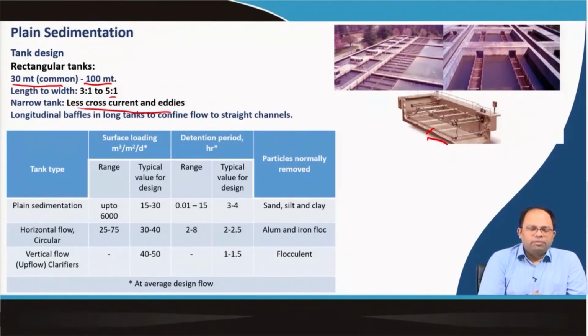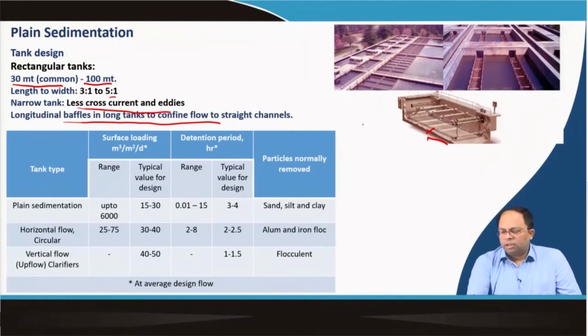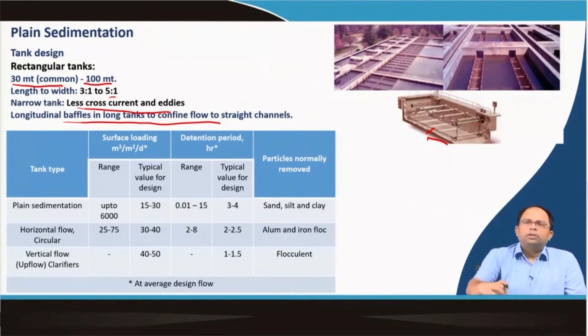We have to reduce the amount of current, and longitudinal baffles in the long tank continue confined flow in straight channels. To make sure that the water goes in the longitudinal way, we give these longitudinal baffles as well. So, these are the basic designs of a plain sedimentation tank, and here you can see the different loading rates and detention periods. Based on this, you can determine the size of the tank. For a plain sedimentation tank, then for horizontal flow or circular tanks, then vertical flow or upflow clarifiers.